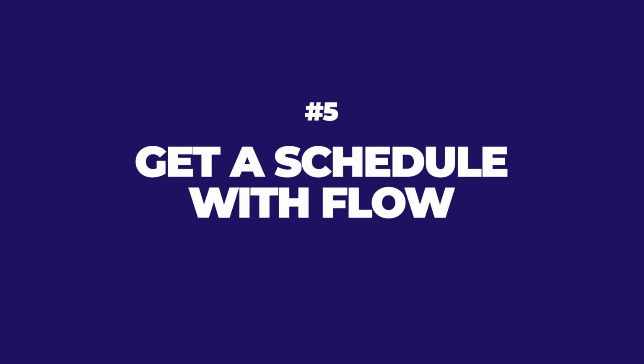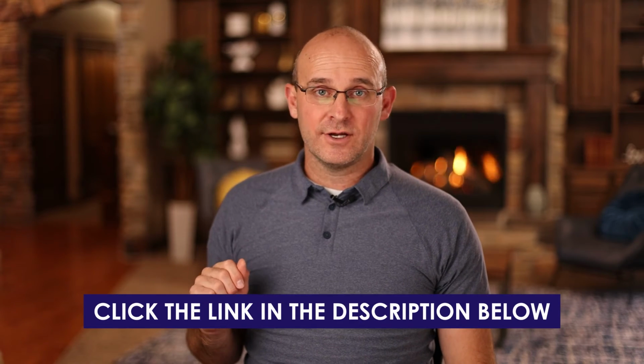Make sure that they have a pre-mobilization meeting, they have a pre-construction meeting, and that you're there for the first in-place inspection for the first bit of work that they do so that you can enable them to succeed. Get a schedule with flow, which means you will have to use TACT planning and Last Planner for your trades. There is no other scheduling system that will do this. I will link you to some videos on how to implement TACT on your job site.